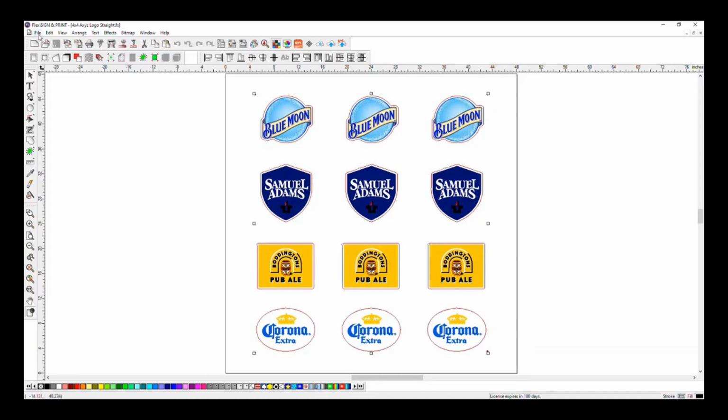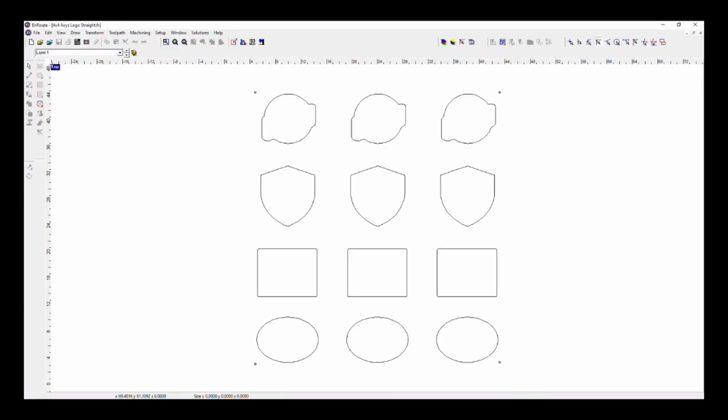Now, if I wanted to, I could go to the file menu and export this for use with any software that can output the AXYZ, but the easiest way to create the output would be to go to Enroute. And so I just hit the Send to Enroute button. What that's going to do is open up Enroute and put these contours on screen.